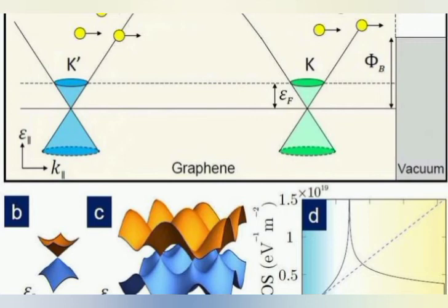After leaving the electron gun, the electron beam passes between a pair of horizontal plates. A potential difference applied between these plates deflects the beam in a vertical plane. This pair of plates provides the y-axis or vertical movement of the spot on the screen. Similarly, a pair of vertical plates provides the x-axis or horizontal movement of the spot on the screen.